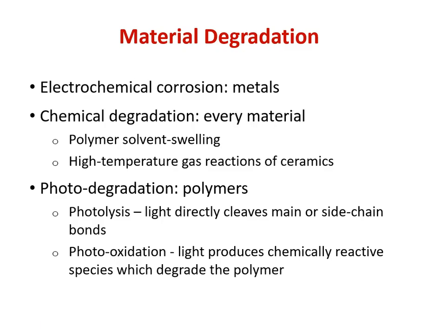We'll give a little bit of mention to photodegradation of polymers, especially because that is, again, like electrochemical corrosion for metals, something unique to that material family. Polymers are frequently used in outdoor applications, mainly because of their electrochemical corrosion resistance, and their very poor resistance to photodegradation is frequently ignored. That's something that definitely needs to be considered for weathering applications outdoors.